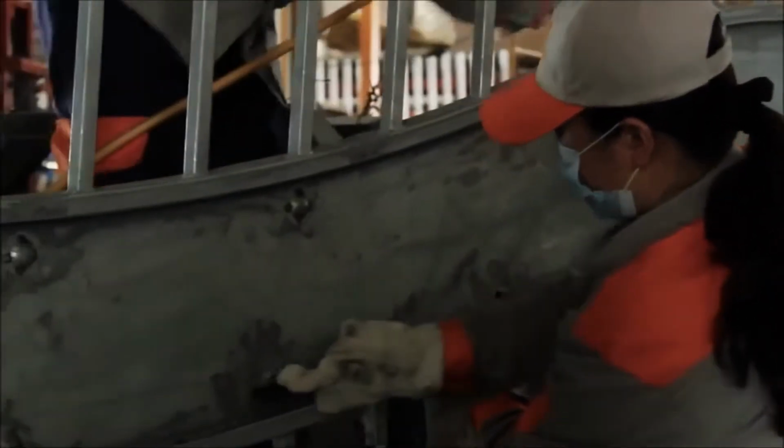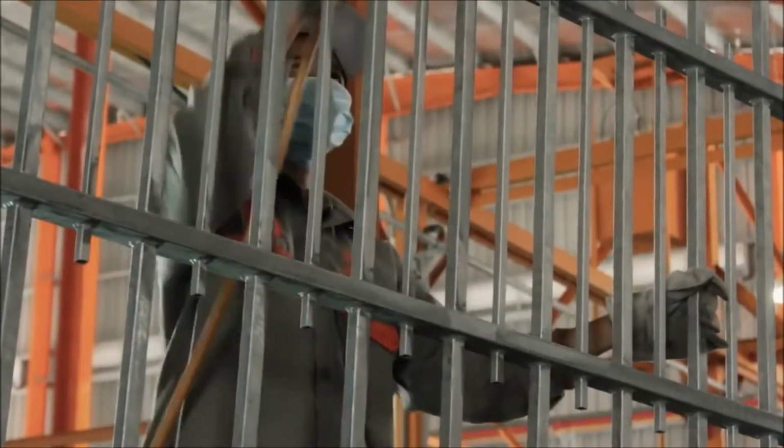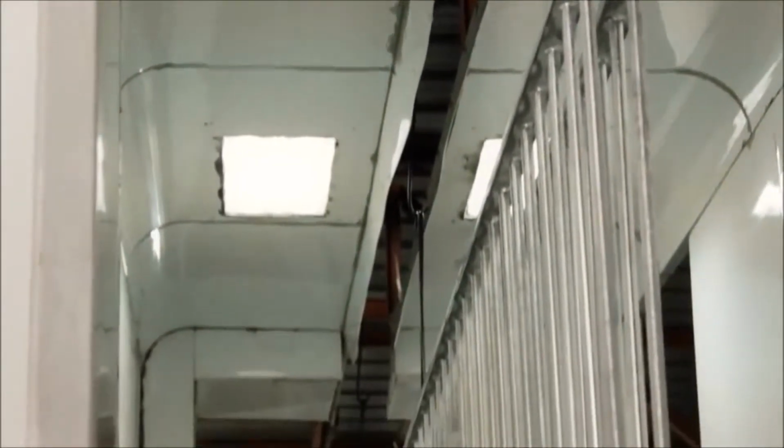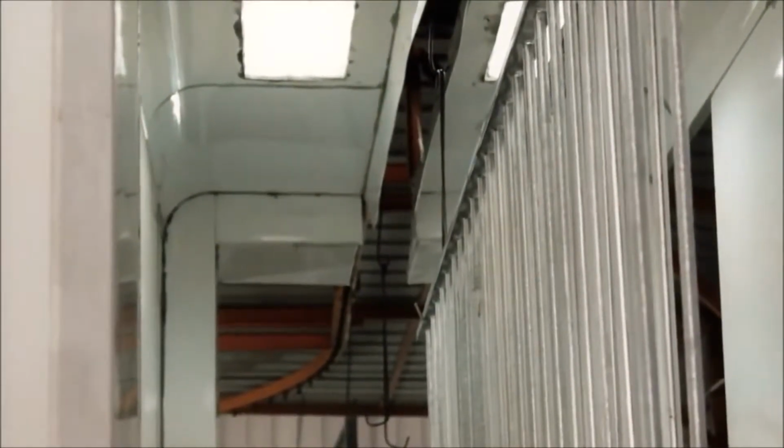So prior to the powder coating of the product, the galvanized product enters into the oven, where the temperature is 200 degrees Celsius. The reason we put the galvanized product in the oven prior to powder coating is that during the hot dip galvanized process, the zinc coating has small little air bubbles in it, which, if not preheated prior to the powder coating, will expand and blow the powder coating off.